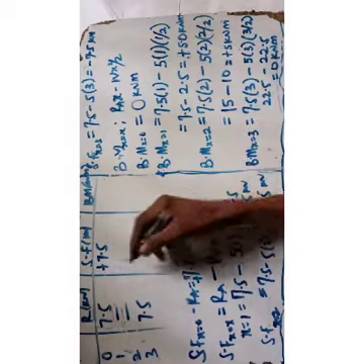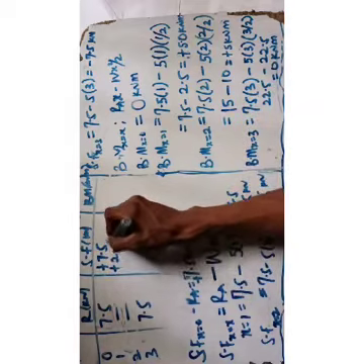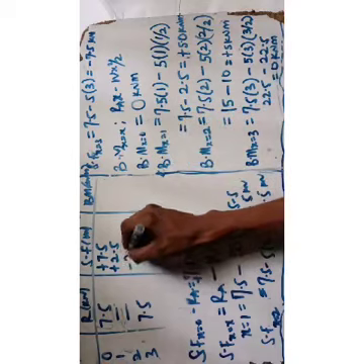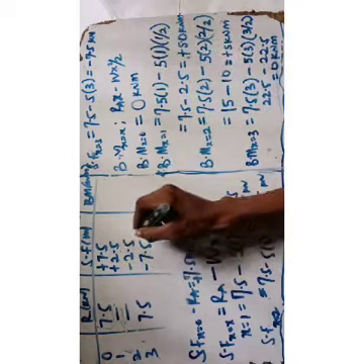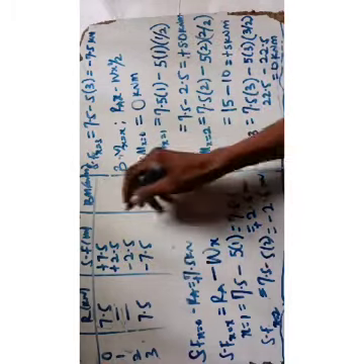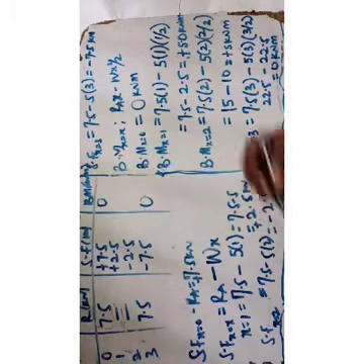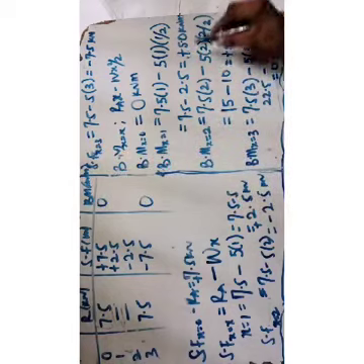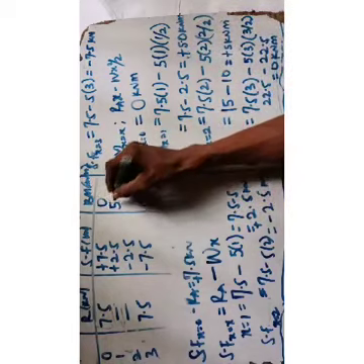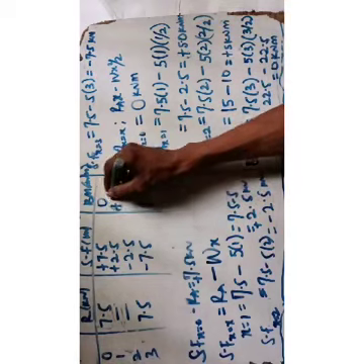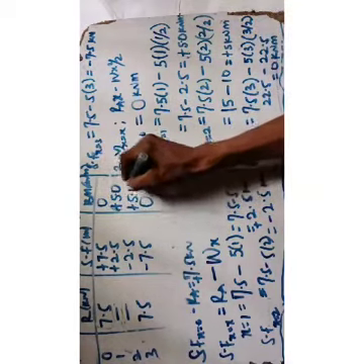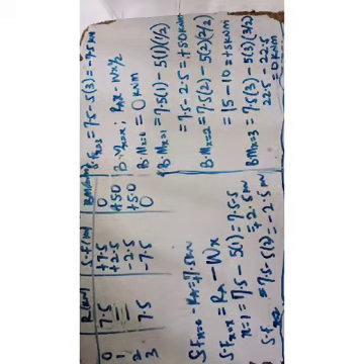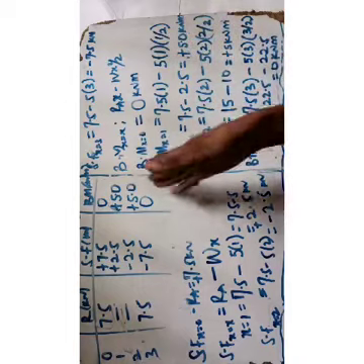When x equals 1, you have it as plus 2.5, then minus 2.5, and you have it as minus 7.5. Bending moment when it's 0, you have it as 0. Here is 0, and at the middle when x is 1.5, that is plus 5.0. Then here you have plus 5.0. I decided to leave it in 1 decimal point throughout. Don't write 0.00, so 5.0.